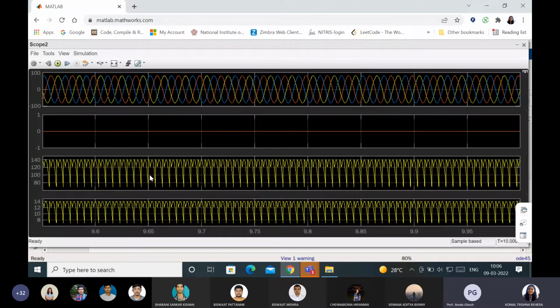The waveform will be the same because there will not be any phase difference, because the load is only R load. Okay, I'm asking about the justifications of your average output voltage. Why are those patterns coming like that? That is my question. That's why I'm telling you this is R load, voltage and current are in phase. There is no doubt on it.